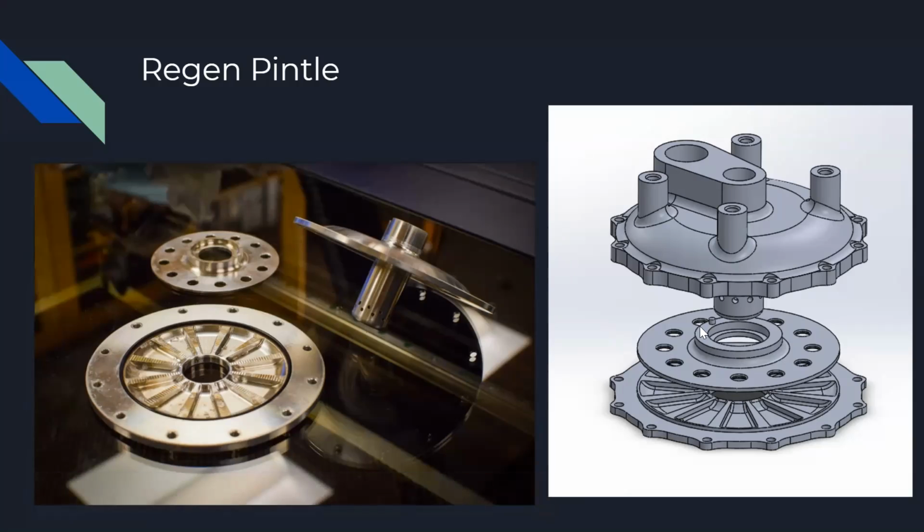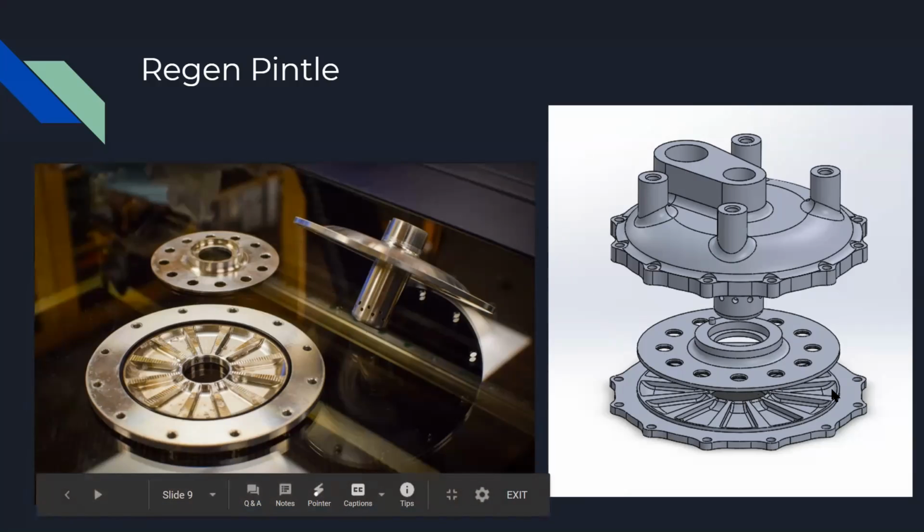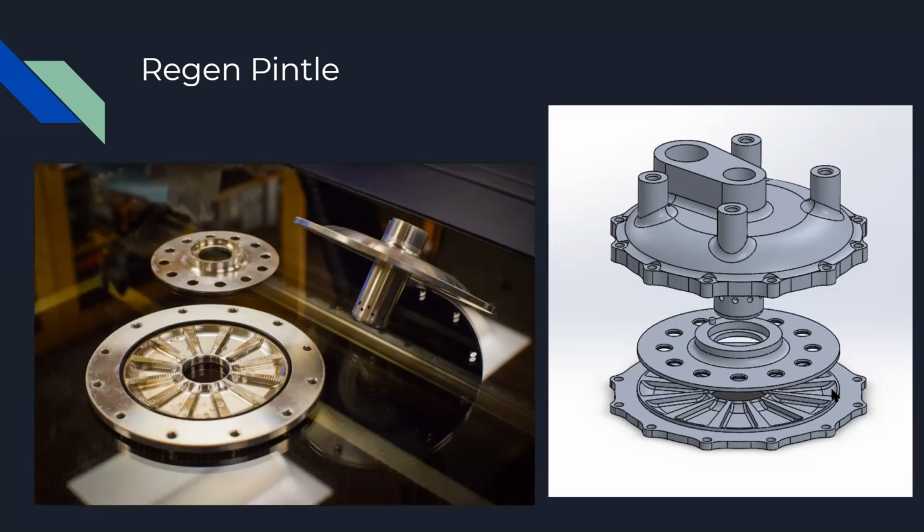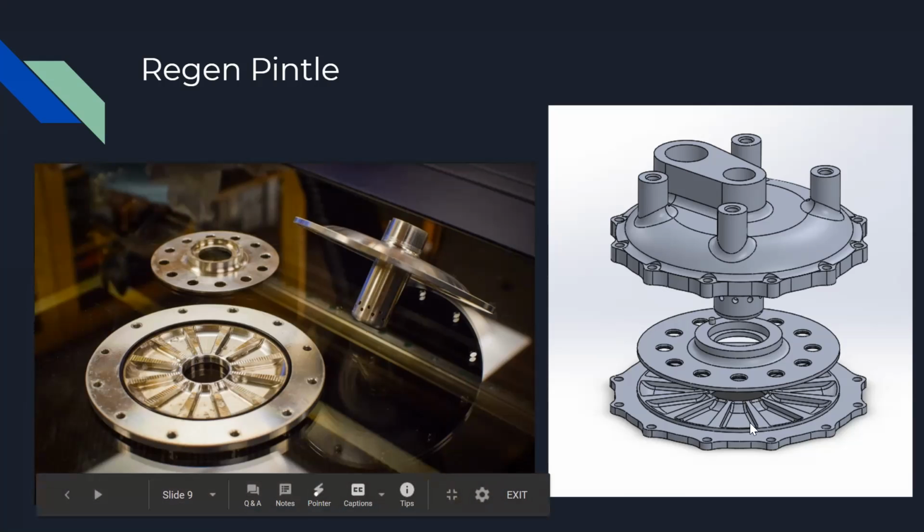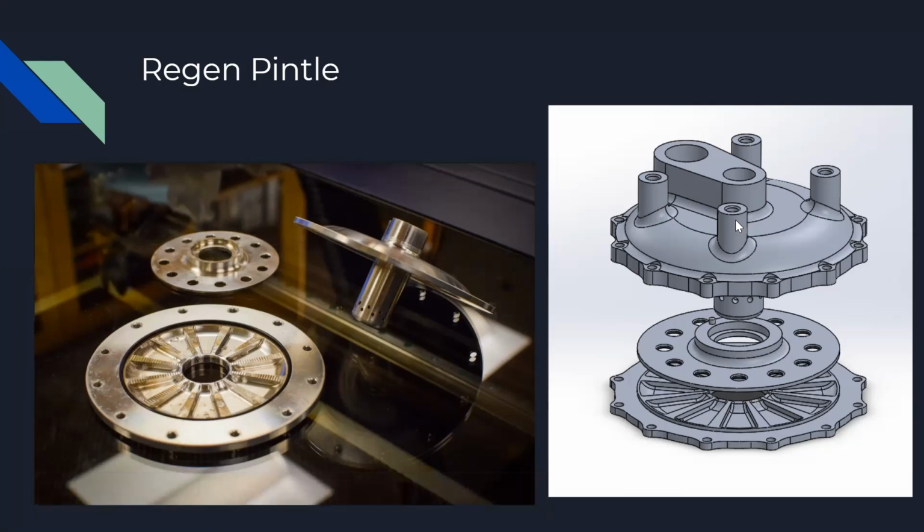Does that with the holes in it in the middle do? Yes, so I assume you're talking about these holes right here. Yeah, that one. So another thing is you want to make sure that all of the flow rate gets distributed evenly around the annulus. So basically here, for us, our fuel is going through the pintle, and then the oxidizer is coming here.